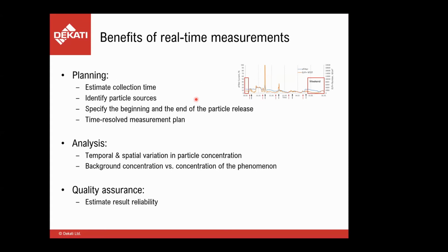And with the real-time data, you can of course do temporal and spatial variation measurements in particle concentration, and very importantly, compare the background concentration, which should be measured before any activity in the indoor dwelling, versus the concentration of whatever phenomenon is generating aerosol into the space.